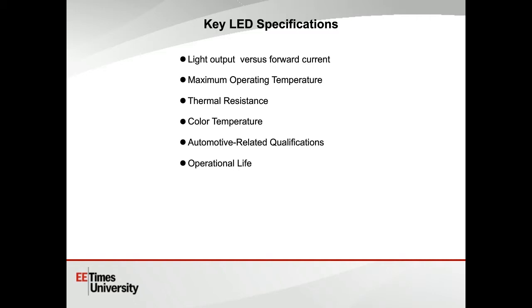The AEC Q100 product specifications are defined in order that manufacturers can test these, and they go inside the construction of the IC to cover things such as wire bond strength testing, gate leakage, robustness to ESD pulses, and so on. And automotive companies test these parts to give a high degree of confidence that the parts will last for an extended period. We're talking 10 to 20-year application life. Contrast that with the life of a typical cell phone, and you'll see that automotive products are pretty tough for manufacturers to meet.